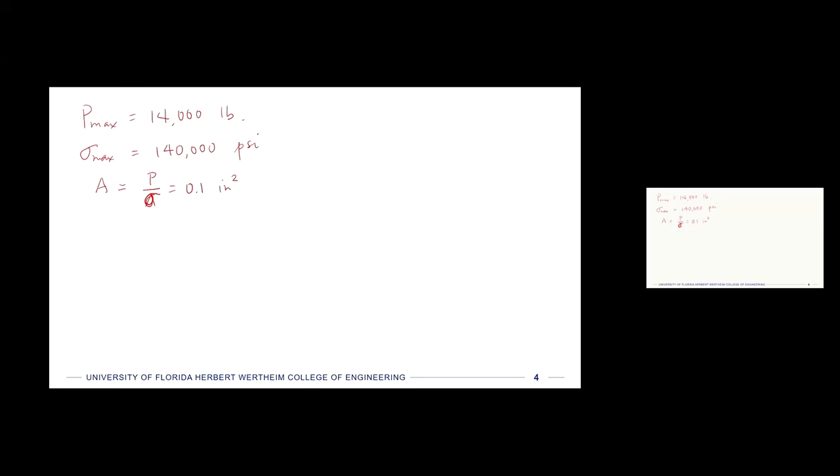So we're going to start with that area, because if that's our highest stress, we get sort of almost no cycles at that stress. But we have a lot of lower stresses that are going to add up to some damage as well. So that's kind of where we're starting. Okay. So if we take that to be the area, then at every load level, we can calculate what the stress would be, because it's just the loads that were given divided by the area that we've chosen. So in the textbook, they sort of transform the whole rain flow diagram from loads over to stresses based on this area here. And so I'm not going to go through the details of it, but it can be a helpful example.